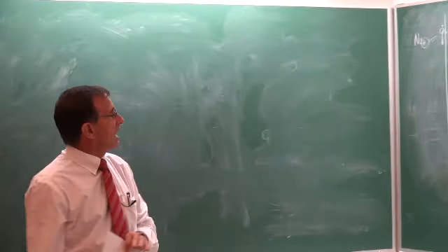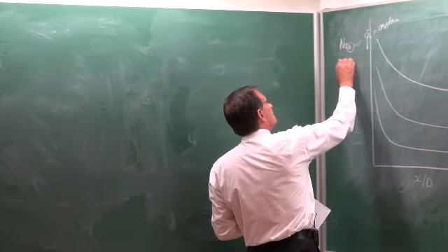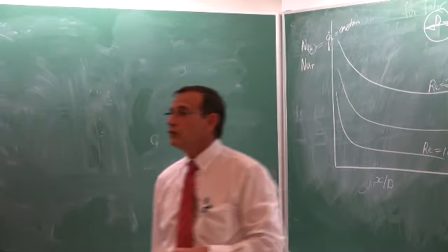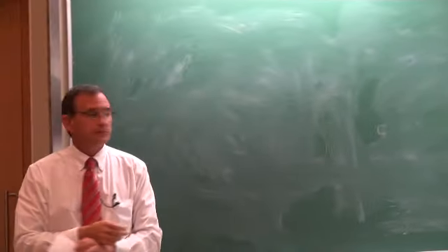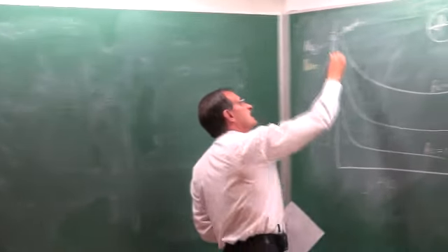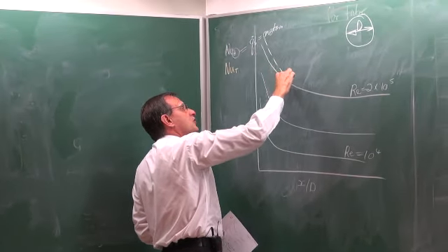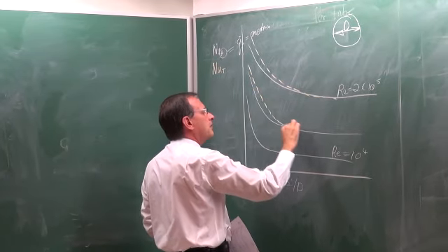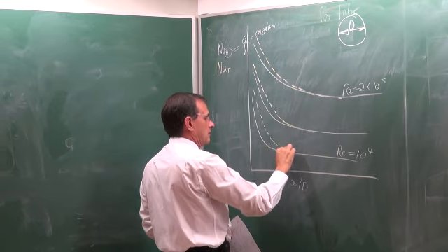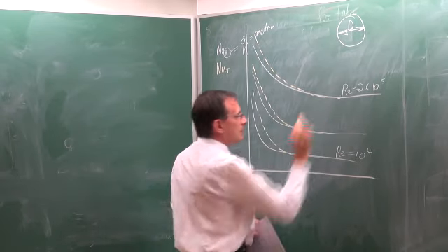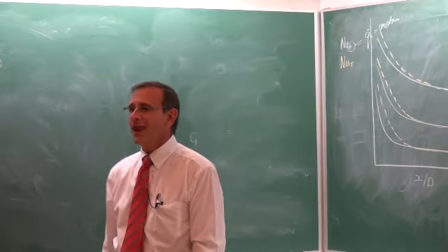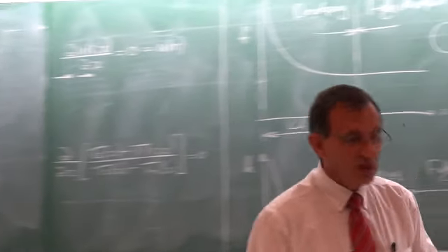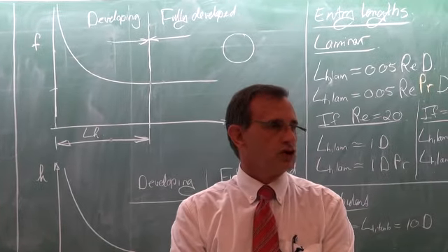If we compare it to the case of, and now I use the yellow to indicate it, the Nusselt number if the wall temperature remains constant. Then what we will see is that in this region here, the results are not the same. The results are not the same, but as soon as the flow is fully developed, the changes are negligible or very, very small.